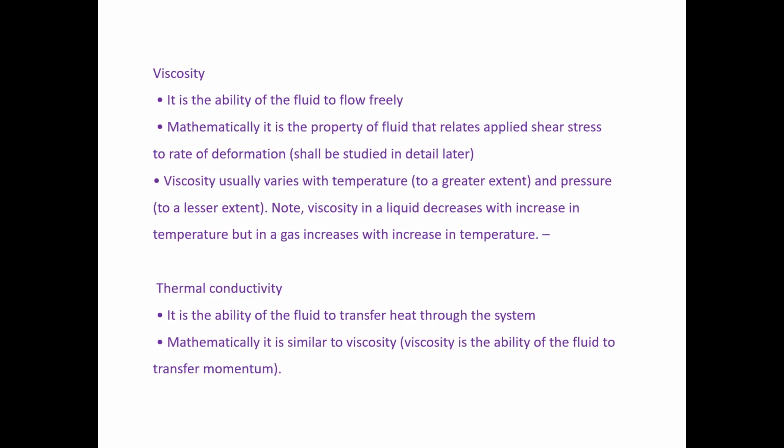Viscosity is a major property of a fluid. Viscosity is nothing but a stickiness property, or the internal resistance between two fluid layers. It is the ability of the fluid to flow freely, and mathematically it is a property of a fluid that relates the applied shear stress to the rate of deformation. Viscosity usually varies with the temperature. Okay, and thermal conductivity is the ability of the fluid to transfer heat through the system. Mathematically, it is similar to the viscosity.